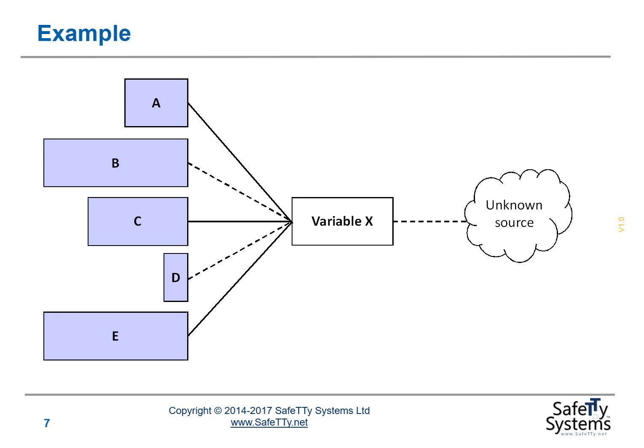But it's possible, because it's a global variable, that task B or task D could also inadvertently or maliciously change the value of variable X. It's also possible that an unknown source could change the value of variable X. For example, some part of a code library that's running our system, a third-party code library that we may not have checked correctly, could also change the value of variable X. Or electromagnetic interference or radiation could cause a bit flip in memory and could again change the value of variable X.